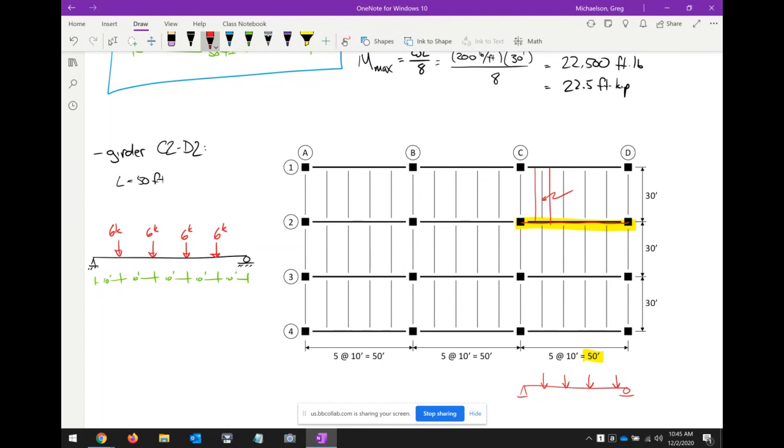Because there's the contribution from this floor beam, but then there's the contribution from that floor beam. And so each one has a 3 kip load on either side. So that girder has got to be responsible to hold up the floor beams from either end. Does that make sense?